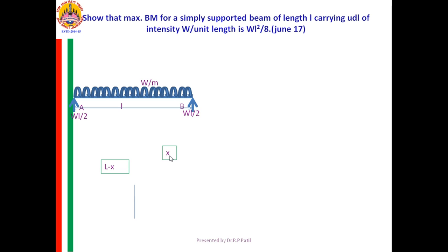First, draw the bending moment diagram. First you try to draw the bending moment diagram, you see what is the problem with you, then you will realize how to solve it. As per the instructions given by me, bending moment means where all you are calculating the bending moments? At left and right of a couple, if there is one; at point loads, and beginning and end of UDL.